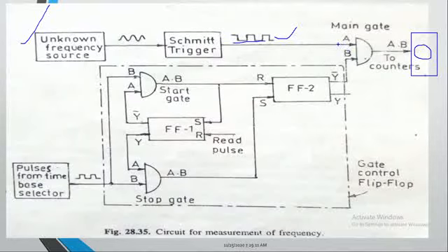These pulses are given as an input to the counter, but whether they are forwarded to the counter or not is decided by the other input of the AND gate, which is nothing but B. If the B input is 1, then only the pulses we are applying are fed as an input to the counter. If the B input is 0, then the output of the AND gate is 0, because as we know, if one of the inputs of the AND gate is 1, then the output is the other input.